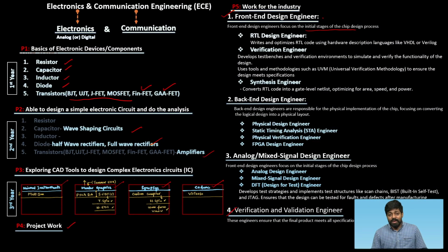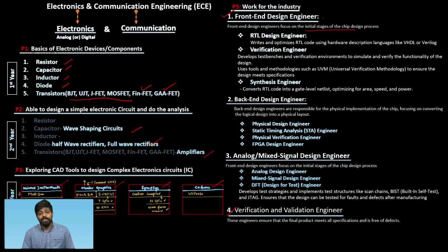And after that, another person called the verification engineer will come into the picture. He will verify whether that particular module, designed by the RTL design engineer, gives the output as per the specification or not. If the number of inputs for the digital circuit is small, he can make a test bench and test it. But if the design circuit is complex, where it needs to be simulated through a complex test bench, then they adopt the UVM technique. Universal verification methodology will be adopted to do the testing.